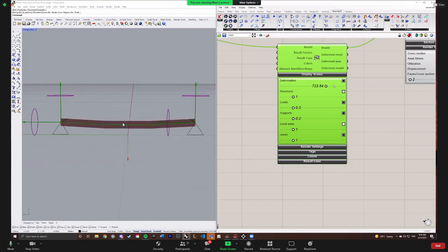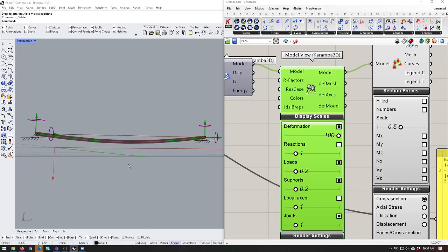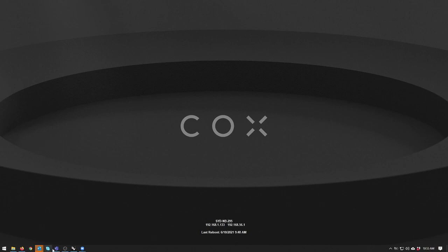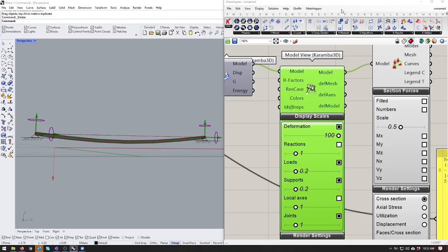Good job. I think it's just a case of a beam that thick isn't going to really deform. It's a 2 meter span. Not under its own weight. Why was yours deforming so much then? Mine's 5 meters. Oh, I thought yours was 1 meter. So if I want to increase the beam size, is it just a matter of changing the length of the line? If you want to change the beam length, then yes, you can just change the length of your line.